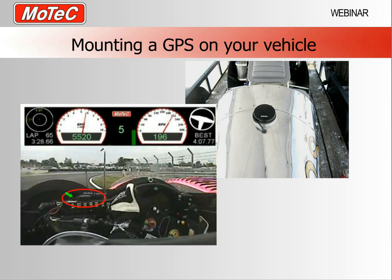But a race car is a different story. A race car, if you are quickly changing direction, will have to quickly hand itself off from one set of satellites to another when the roof of the car, if you're in a closed car, starts to interrupt the signal from the satellites that you were previously using. This isn't such a problem with a slow rate GPS such as a road car based GPS. But on a race car, you need to keep as many satellites and as consistent which satellites you use as possible at all times.